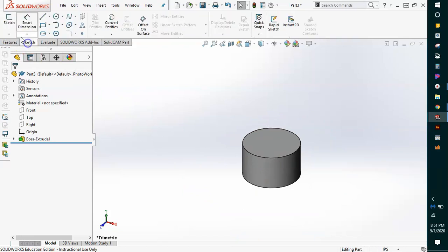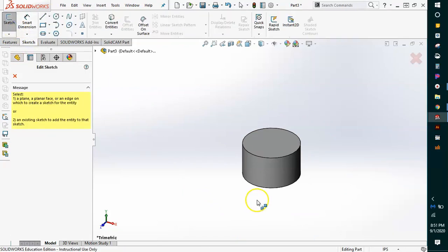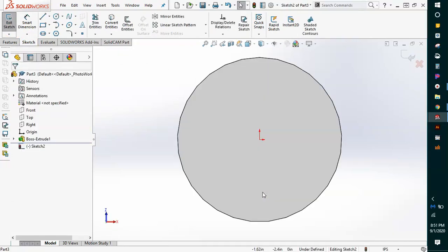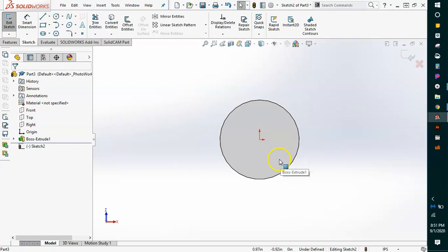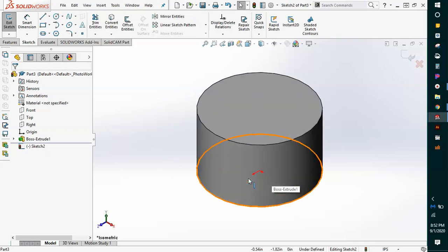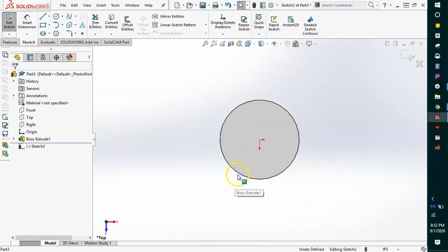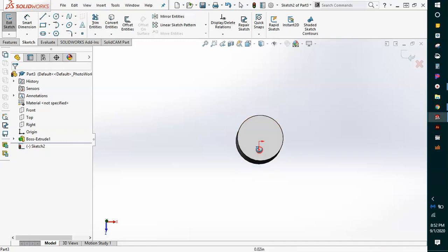And now what this allows me to do is actually sketch on the bottom itself. So if I rotate around and sketch on the bottom, okay, if I hit Control 8, it's going to rotate me to this. Now, you might draw it looking at the actual part, but what I can tell you is when you go to a 3D view, you are actually upside down. So if I hit Control 8, I'm looking at it upside down, which means I'm kind of going to be drawing backwards. I actually like to hit Control 5, and what that does is it gives me an aerial view. So now I am on top of this, as you can see, looking down at it. So Control 5 gives me a better view, okay?